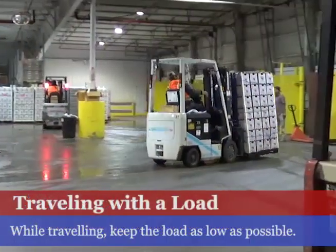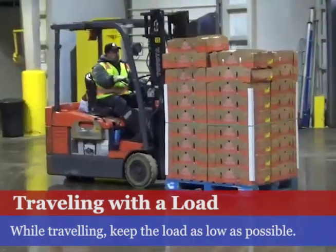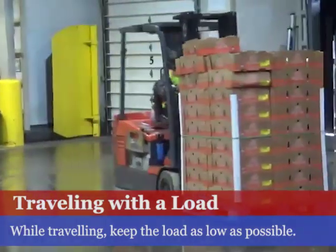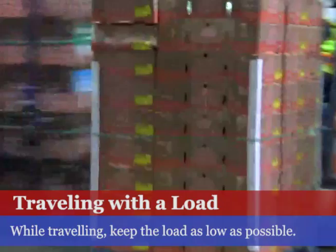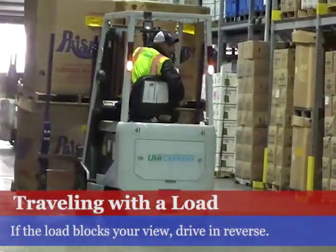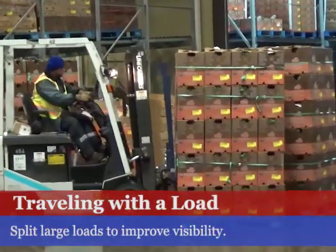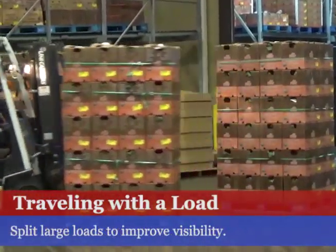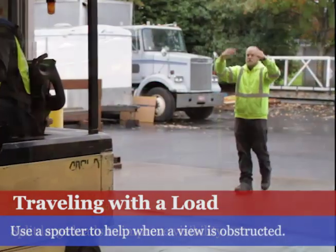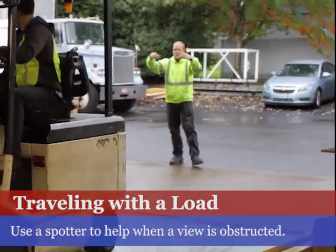When traveling with a load, keep it as low as possible. It only needs to be raised enough to safely clear the ground. Keeping the load low will help the vehicle remain stable and balanced. If a load blocks your view, drive in reverse. If possible, split or rearrange the load to maximize visibility. If the view is obstructed, use a spotter to help guide you.